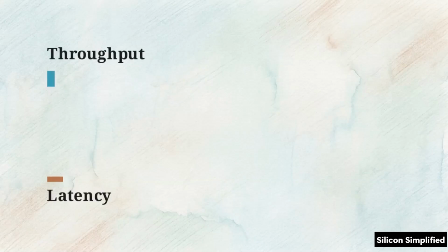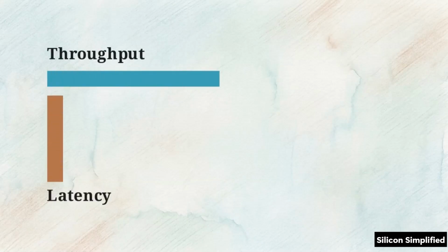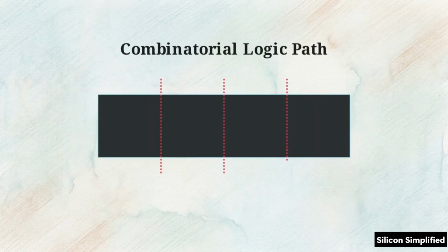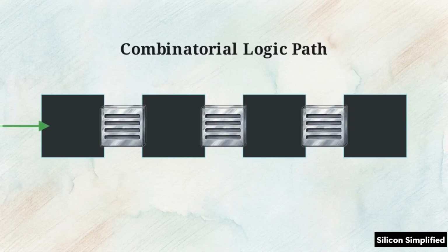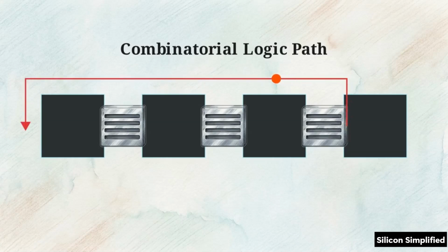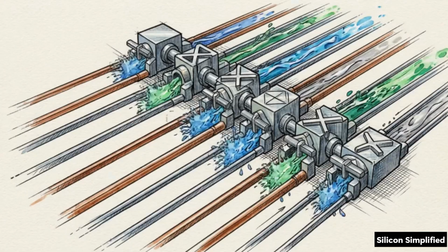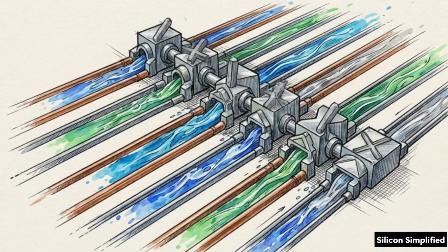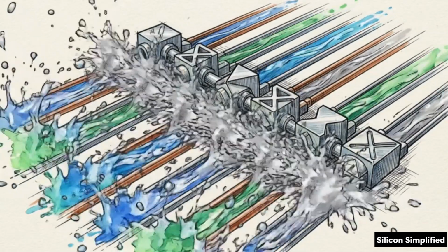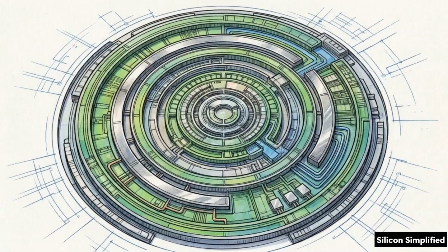Pipelining increases a system's clock frequency by trading cycles of latency for sustained throughput. We slice a long combinatorial logic path into segments by inserting sequential registers to bank data between clock cycles. This creates data dependencies. Routing a feedback loop backward across these registers delays the signal, clashing with incoming data. Relying on the two-step update of non-blocking assignments manages these temporal shifts, resynchronizing the data flow at each clock edge. Pipelining scales the simulation event queue's mechanics to the system level.